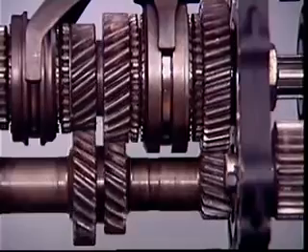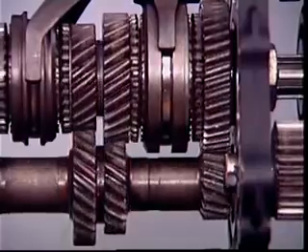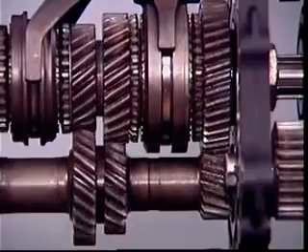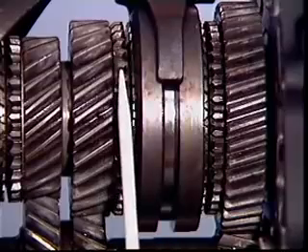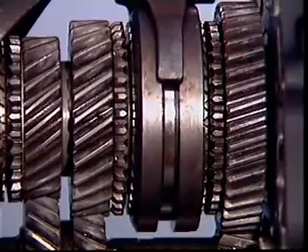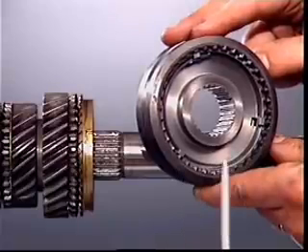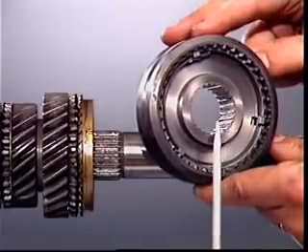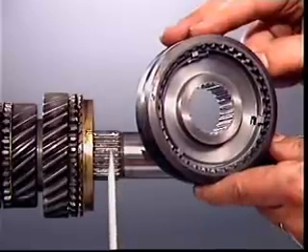These main shaft gears are supported on bearings on the shaft. They can rotate without turning the output. Each main shaft gear has an external toothed section on one side. The teeth face an internally toothed engagement sleeve located on a central hub, which is itself splined to the main shaft.